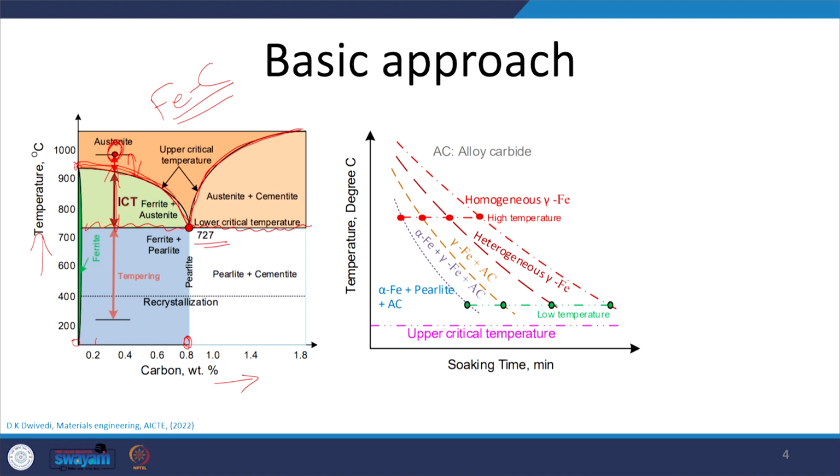Okay. In addition to these heat treatments where heating is done above the upper critical temperature, say upper critical temperature plus 30 to 40 or 50 degrees centigrade for achieving the homogeneous austenitic state, there are other lines. This is the tempering temperature line, and this is the range also for our stress relieving conditions.